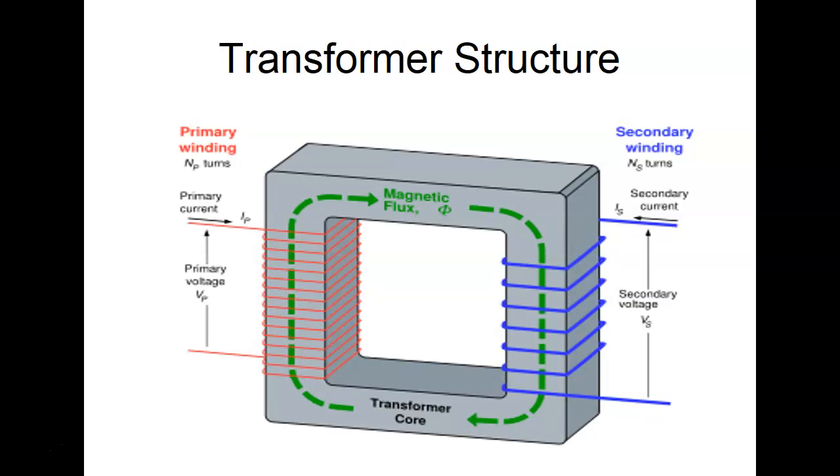So basically the way we do it, we have a primary. It's got a change in magnetic field, right? It generates a magnetic field. The magnetic field is coupled over here to the secondary. So the magnetic field will cut these windings and induce a voltage over here through induction, right? Just like me doing what? Swinging that wire over here. But here the magnetic field is being produced by electromagnetic induction. Now, what determines the amount?